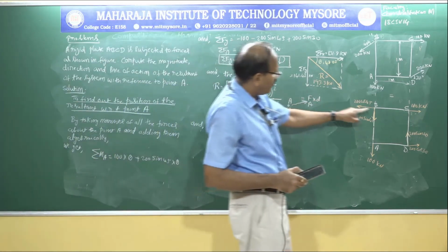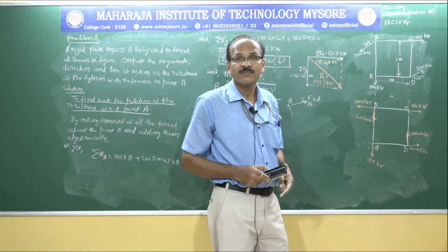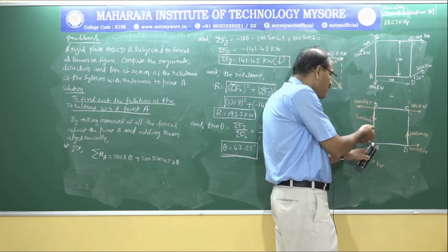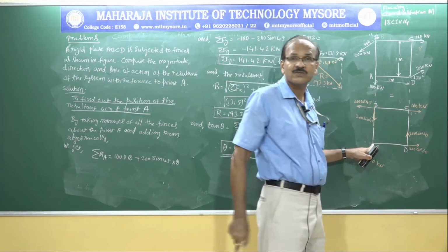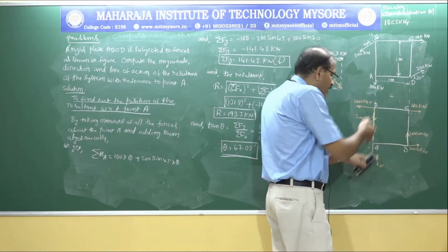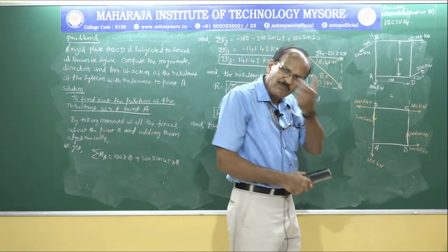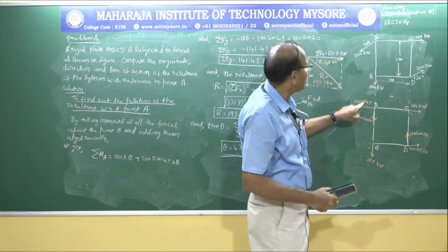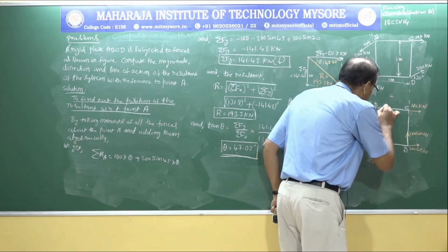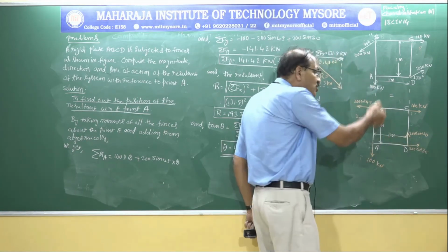So next I am going to go to this force. This is the line of action of this force. This cannot be 0, because from point A, if you draw a perpendicular line, there is a distance, that is 1 meter. And this force is causing a counterclockwise or anti-clockwise moment about the point A. This gives some value, that is 200 cos 45 multiplied by this perpendicular distance, which is 1 meter. Of course this is 1 meter and this is 1 meter as well.